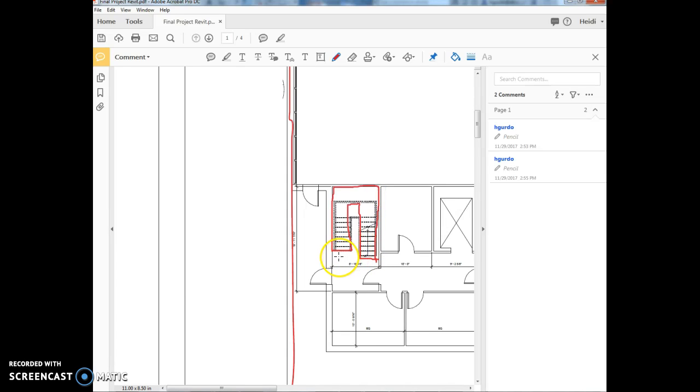Also, make sure that you think about those guardrails that we talked about in the textbook. So I believe that was Chapter 6 reviews railings and stairs. So you want to make sure that you review that chapter because you have to add some details here, like the railings are supposed to extend a foot past in this location. So go back and look at, I think they call it lesson 6, not chapter 6. So that's one thing that you'll have to update here.